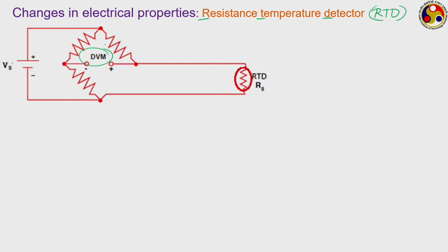Now, this circuit, or this voltmeter, can operate either in the deflection mode, just to indicate how much deflection has taken place, or in the null mode, where we get the bridge back into the null position and correspondingly try to calculate how much effort we have to put in to get this null position. Either of that can give you a measurement about the change in resistor, and that can be related to the value of the corresponding temperature, because we commonly know that the resistors or